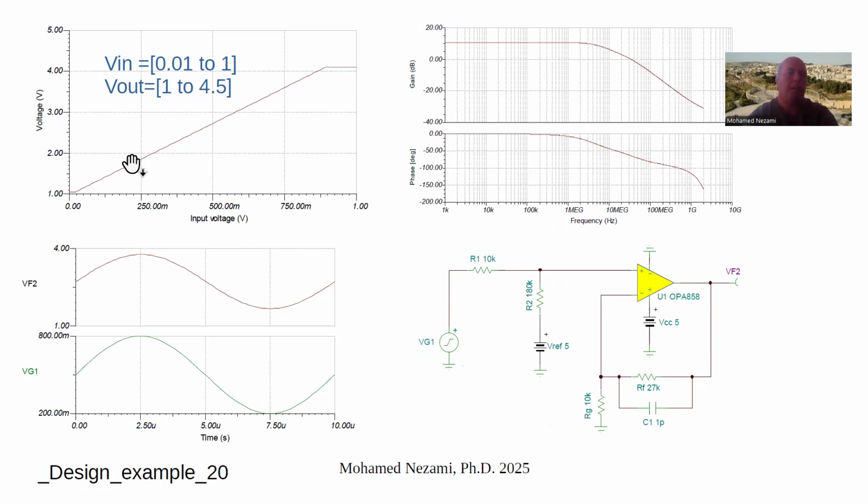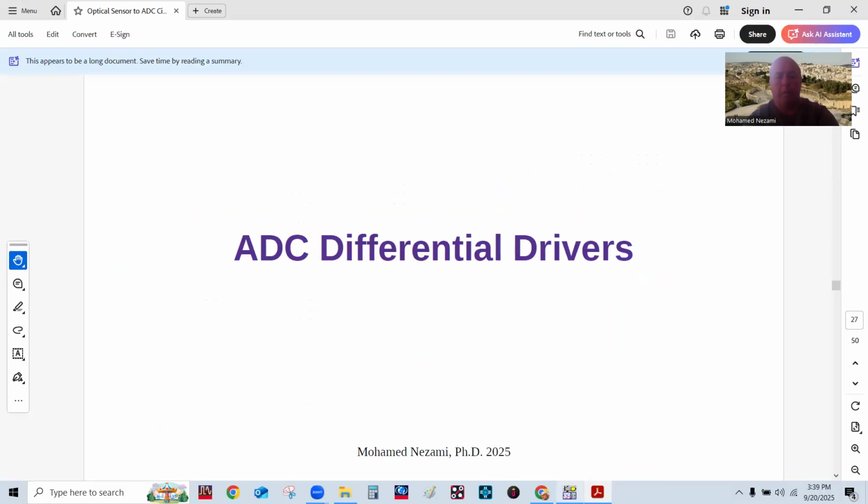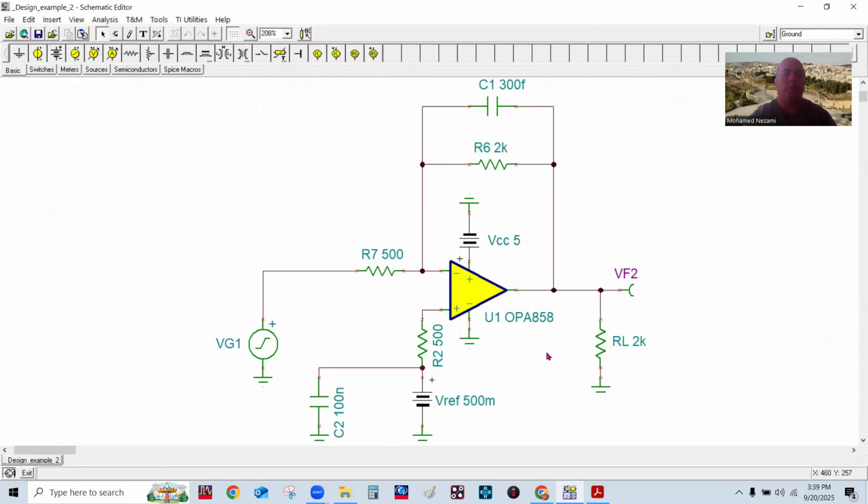You can see that with an AC signal as well, and the gain. You can see it in here. So let's run this. Let's do this one here. The first thing we need to do is just calculate the DC point. So 2.5 volts. That's the DC offset right now.